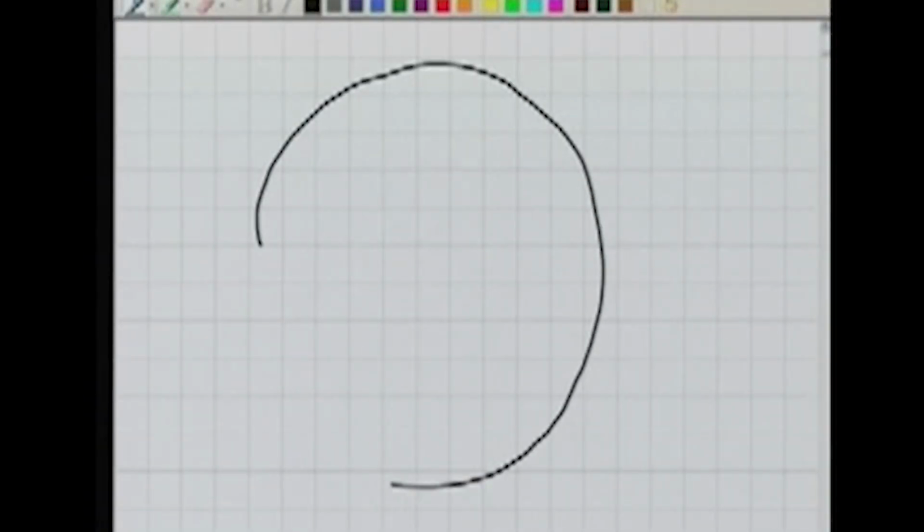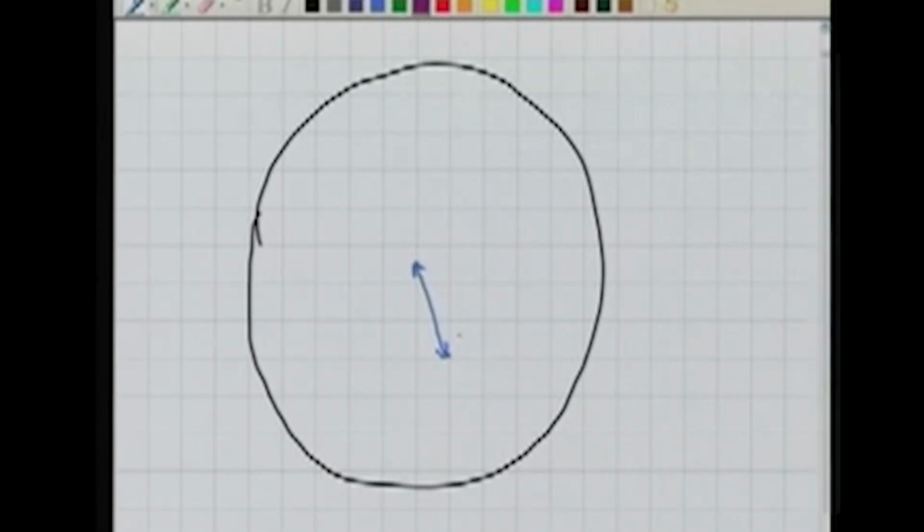Let us say this is our horizontal circle or the lower plate, and this is the actual center of it, or the center of the lower graduated circle. Now on this, our verniers have shifted here. There is an eccentricity in the centers of these two circles. Now any angle that I measure now, let's say the ranging rods are here and here as in the previous case.